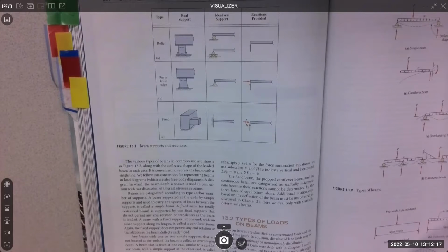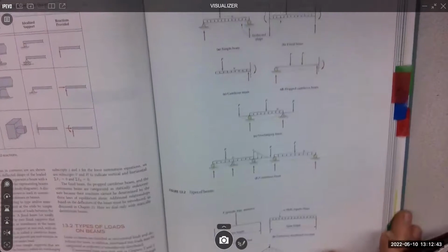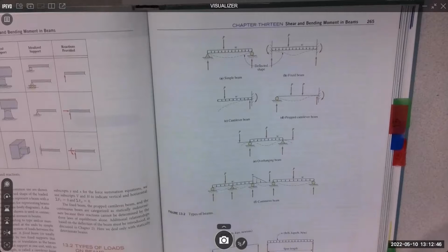I mean, we have a bunch of concrete, but then we pin the bridge to the concrete, right? So really the only time we have something super solid and fixed, it's like some kind of welded thing, you know, stick something on the wall, weld it, bury something in the wall. Sometimes you'll see cantilever beams coming out of walls that have been built into the wall or the structure. Any of those kind of things will carry a moment. So they give you kind of the overall basics of what we work with over here.